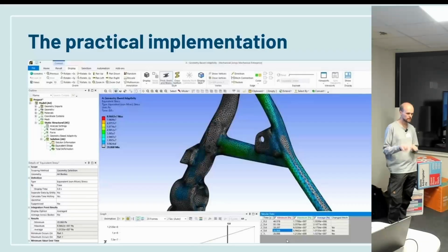If you do something like a voxel grid, you get elements which are very oddly shaped. That degrades the quality of the differential operator in that. So all your solutions which represent the derivative of your solution, and the stress that we are after is the derivative of the deflection that we are computing, that goes out of the window. And second, you cannot have hanging nodes. Every node must land on other nodes, not somewhere inside a face or on an edge. That also gets pretty complicated very fast.